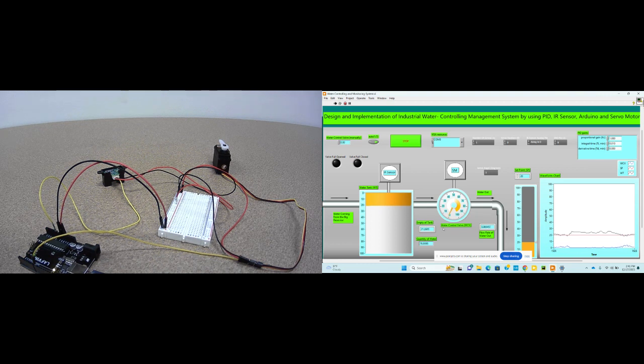The same thing also happens if we decrease a little bit, like 10 points. Let's make it 10%. That means we want 10% emptiness, and we want 90% of water in the tank. But right now how much quantity of water do we have? 74, but we need 90%. So we already have a shortage of water, that's why the water control valve is fully closed.